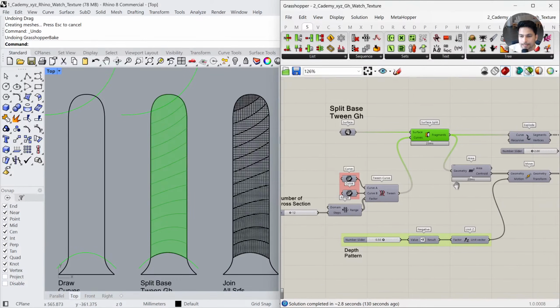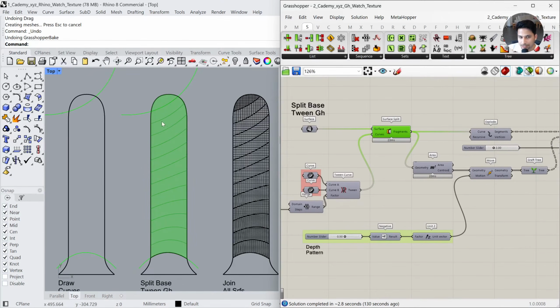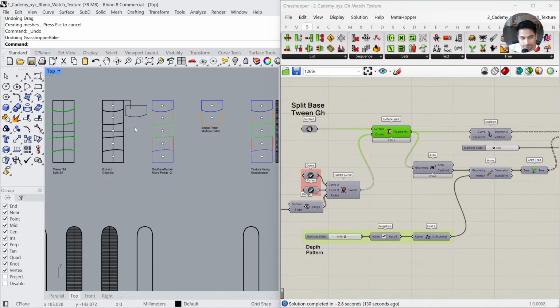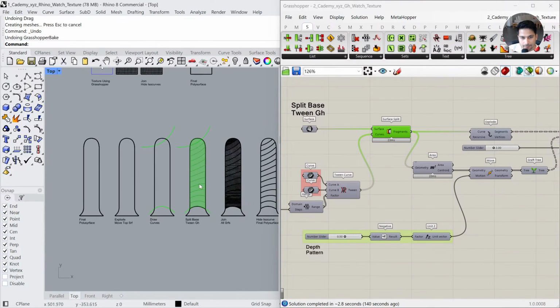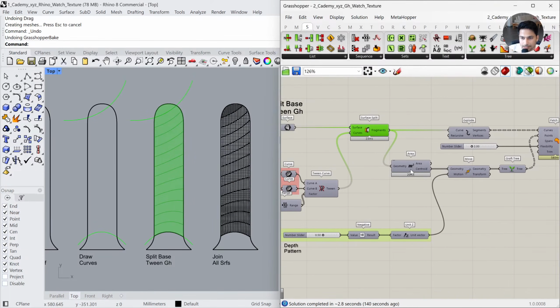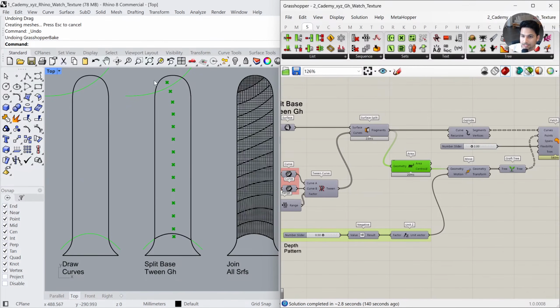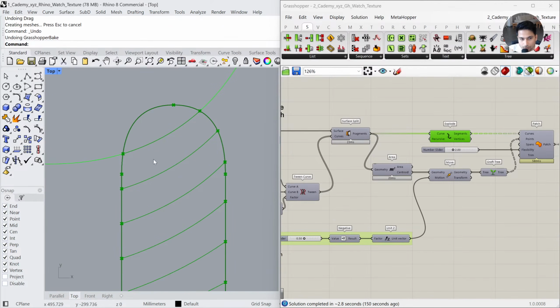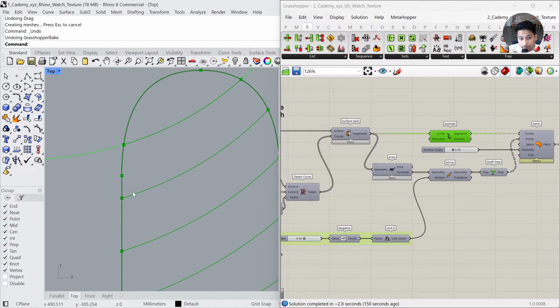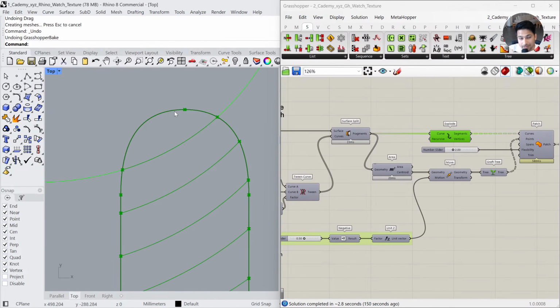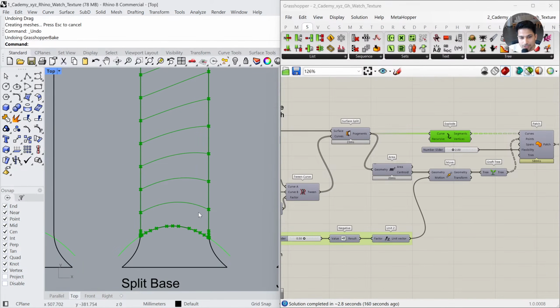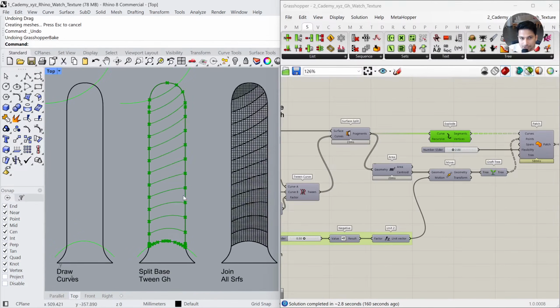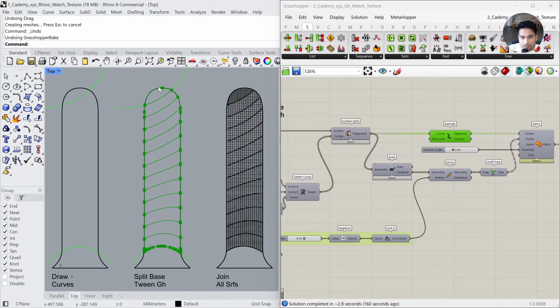All right. So now we have the trimmed surface like before. Then I selected the centroid, as you can see easily. And I selected the curves. And you can see there are curves where we have 4 boundaries. There are curves where we have 5 boundaries. There are curves where we have only 3 boundaries. So this is the advantage of using the patch command. The total number of boundaries doesn't matter.